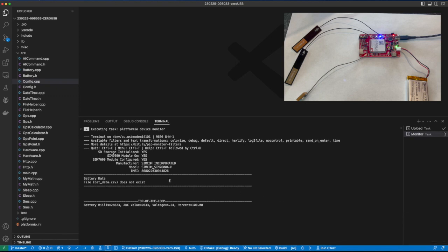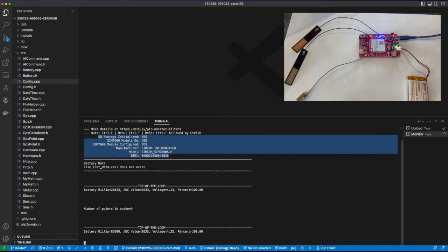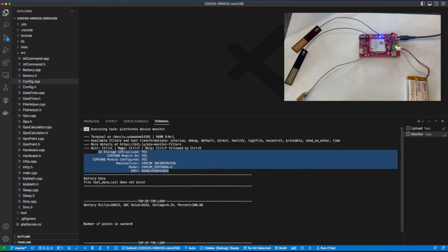So if we look at what's on the output, once the board's restarted, we can start to see some of our output here. It didn't capture the right in the beginning because at the very top, sometimes the serial port isn't open for USB, and so you're writing to it and nothing's showing because it's not quite initialized yet. But you can kind of see the trailing edge here. The SD card's initialized, some 7600's initialized. You can see the hardware IDs.